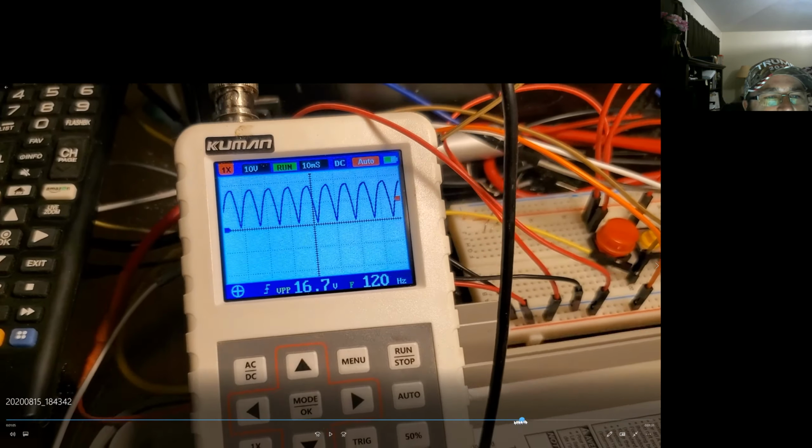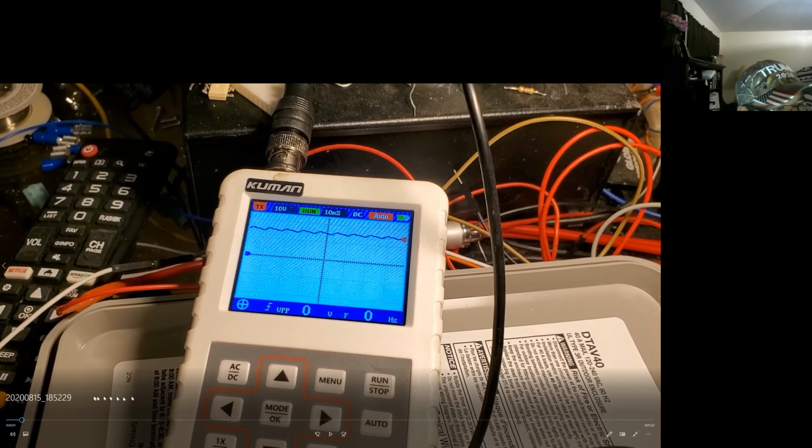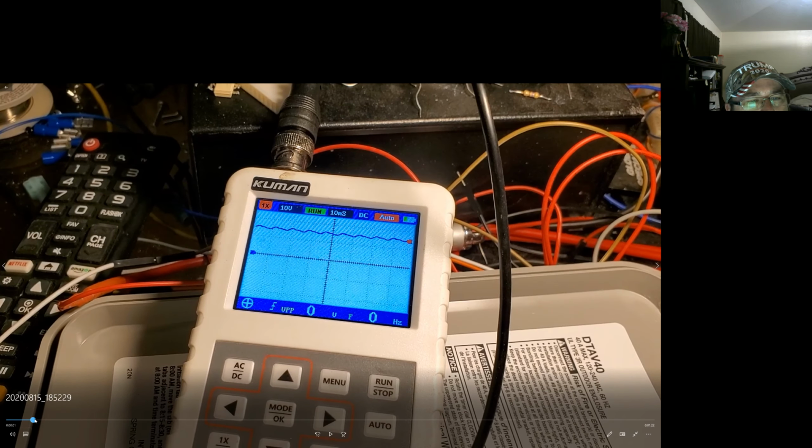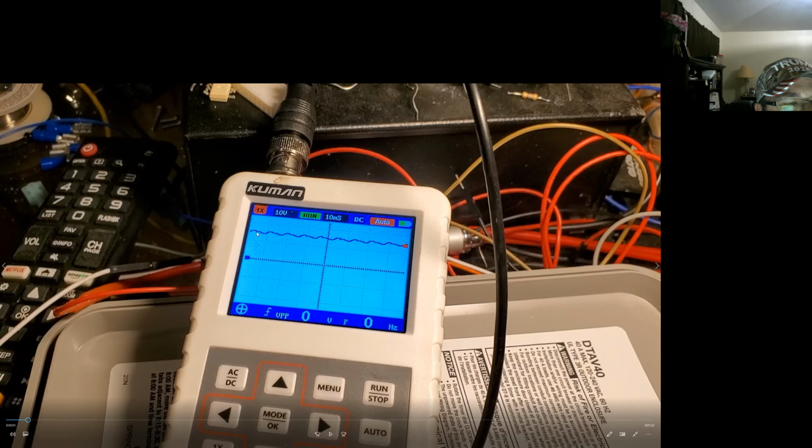So you have to hook it up to a load. I don't think it's in this video clip. So here we go. I had to stop it to hook it up, but now you got a ripple. What that is, it was leveled off up here, remember, which was the peaks of the sine waves. But I've got a fan hooked up to this as a load. So as soon as the sine wave drops down, it's no longer charging anymore. You're not off the grid power, right? Because the sine wave's going down before the next hump right here.